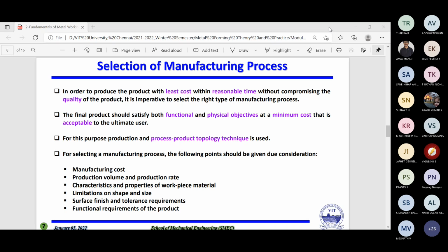We have to calculate. We have to instruct the PLC people that you have to add this much coke now, this much iron ore now. If the liquid metal composition is a little different, you have to tell whether the liquid metal is, let's say, a little cold. Cold in the sense this is not like 0 degree or 20 degree. Cold means the carbon composition is less. So in that technical aspect we have to tell them to charge coke now so that the metal will be hot, which means the carbon content will be more.